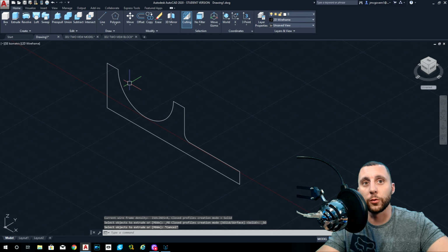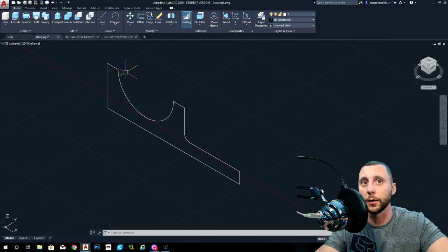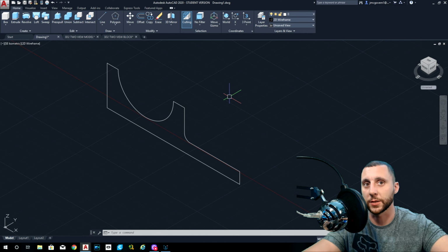The reason why I did lines in the beginning and not polylines is because if I did a polyline here, here, and then there, that would have become one line and one shape, and I wouldn't be able to do my 2-point and delete that line out of there, okay? Just like I said in the first video, you wouldn't be able to do offsets or anything like that when you need to. So most of the time polyline doesn't really work. It's usually lines that work, okay?